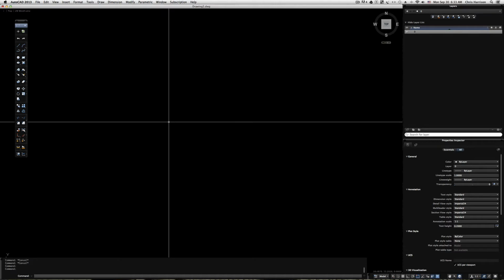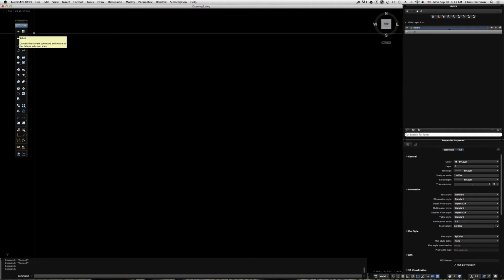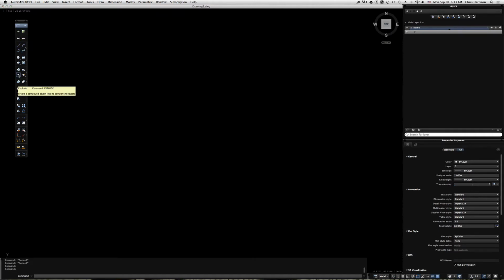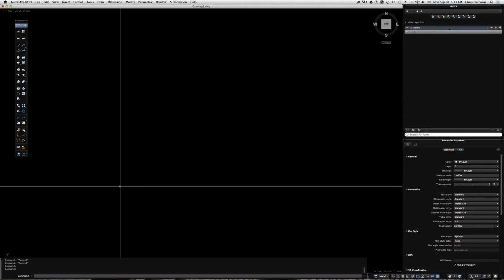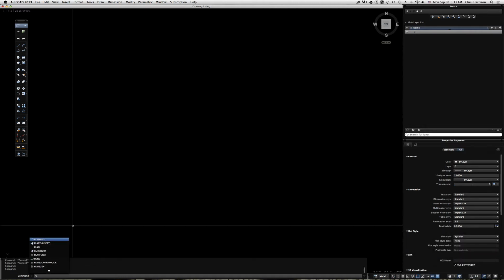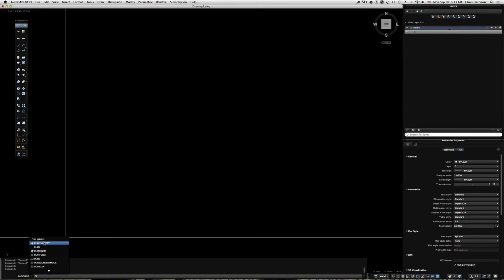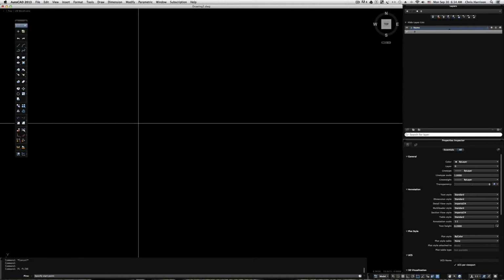multi-view shapes. To activate that tool, I use a lot of shortcut commands, and this is typical with AutoCAD in general. You have the ability to click on these graphical user interfaces, or type things into the command prompt line, or just type them in. So in this instance, I'm going to hit PL for Polyline, and you see as I do that, on my Macintosh version of CAD at least, it begins to display potential actions or elements that PL coincides with. In this instance, it is Polyline.